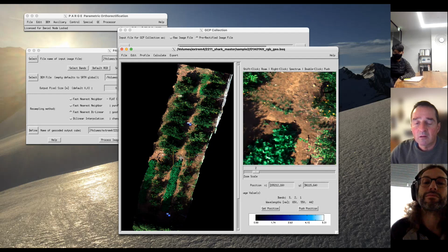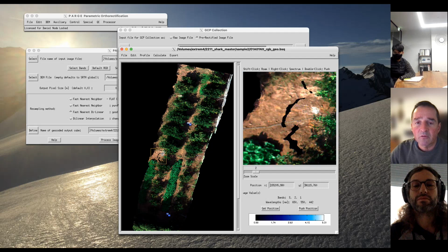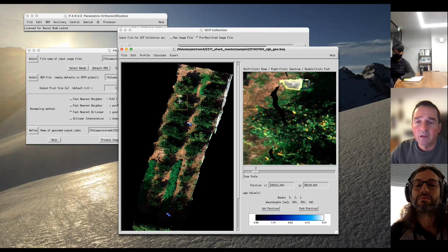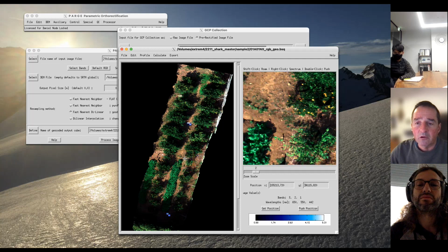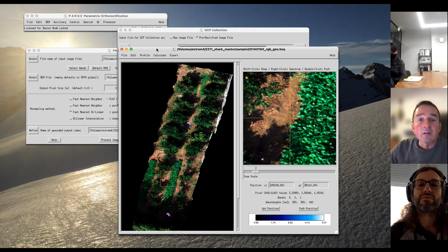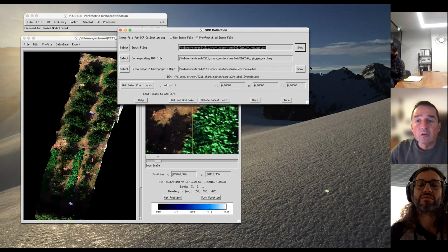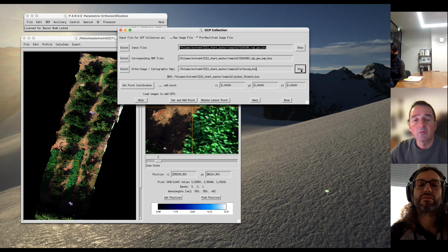In here, I got these ground control points. This one was based on the digital surface model, but you could also do it on the flat ground. So you have a few points I already have searched before. And then at the same time, you load the auto image.